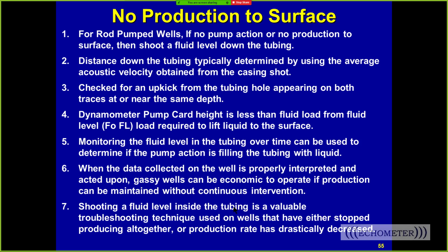A long time ago, when I first started using fluid level data, all I really wanted was a pump intake pressure, producing well pressure. But sometime in the past, it's been quite a while, I realized that I can see down there. I can see what's going on. I can see a problem. I can see kicks that aren't supposed to be there. They're there, but they're indicating a problem when they're there. So the acoustic instrument is a great tool to do inexpensive troubleshooting of your well.